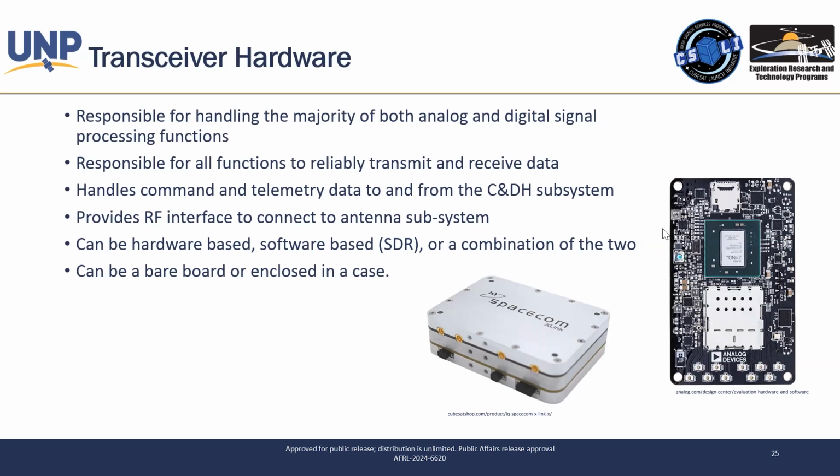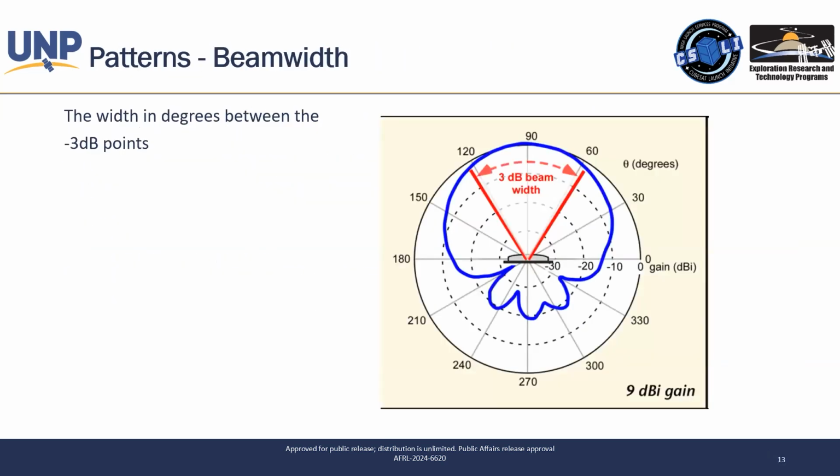Yeah, so let's go back. When we talked about this, typically the way we measure our antennas is by a 3 dB beam width, which is the same thing as a half power beam width. So 3 dB is the same thing as 1/2. When we measure that 3 dB beam width and then ask what the ratio is to our perfect isotropic radiator, that's how we get our half power ratio. It's in dBi. That's a great question. Are there any other questions?